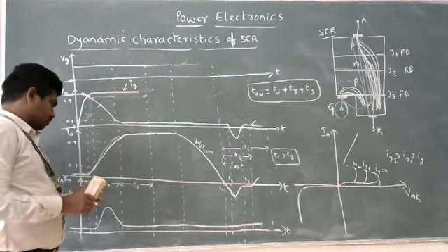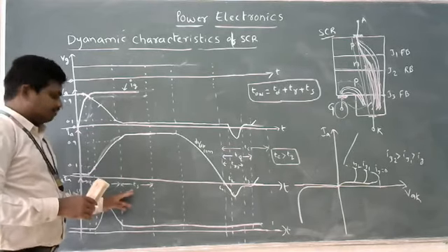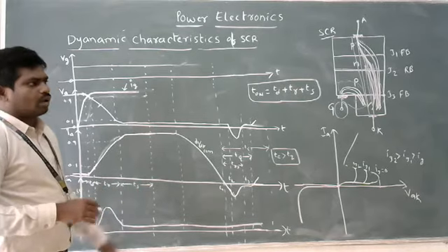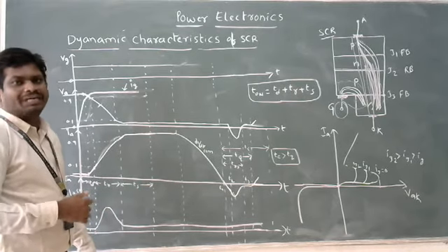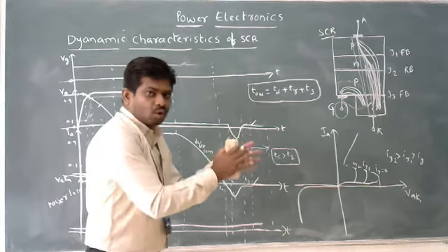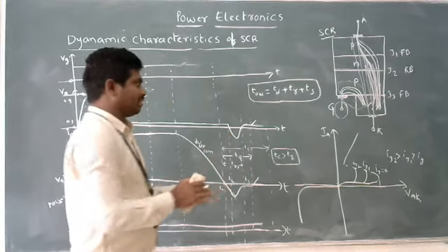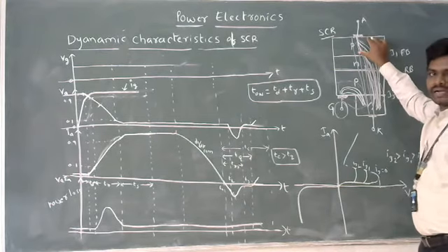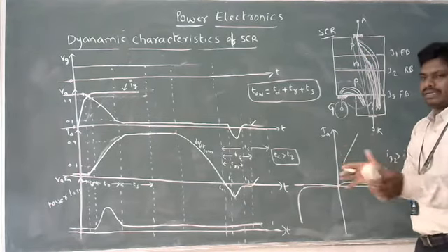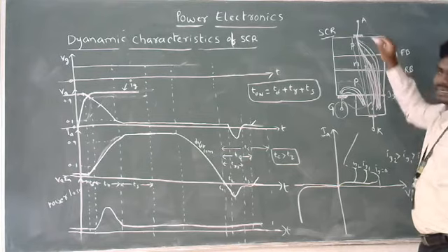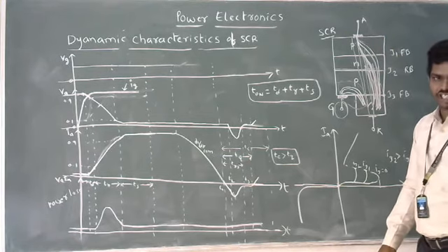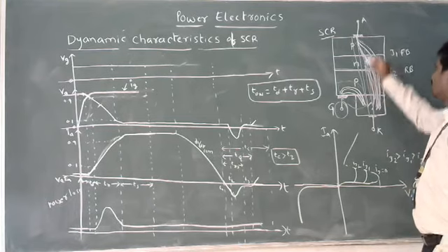These are the characteristics. After that, we have the spreading time. What does it mean? Spreading time means our current flow in the device is going to be spread over the entire device. The time taken by the anode current to spread over the device is nothing but the spreading time, and we can say that is a peak time also. Sometimes we can mention peak time also.